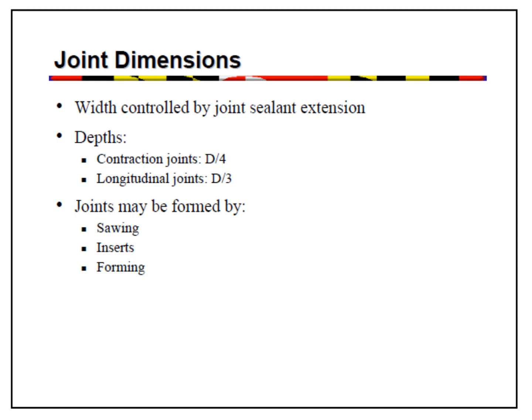If you look at the formation of the joints, joints can be formed in two ways generally. Contraction joints are most often sawed in after PCC placement. Others such as expansion, isolation and construction joints are created by formwork before the PCC is placed. Each one of these methods of joint construction has its own method and set of considerations.